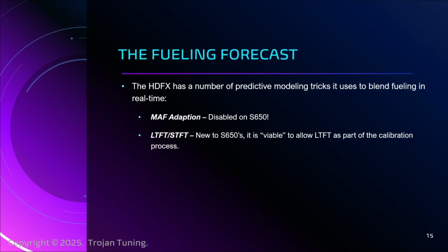Lightning fast, but long term, because it's a little quicker, you can do blended averages and you can do calibration, especially because we're in closed loop so much. You can look at LTFT and STFT combined in some cases. Now, it's not necessarily the best practice, right? But it's a good hack, and you can get away with it because the ECU is so quick.